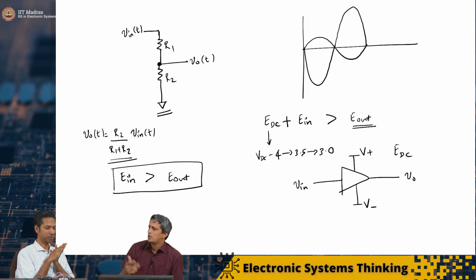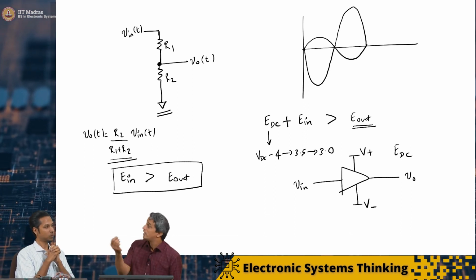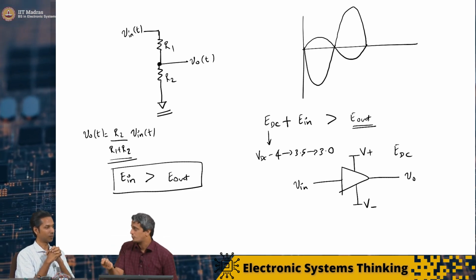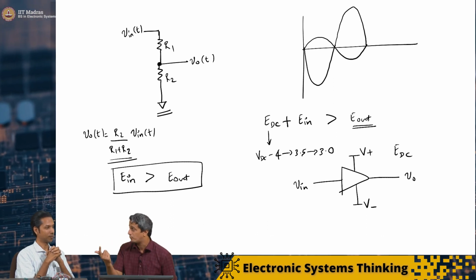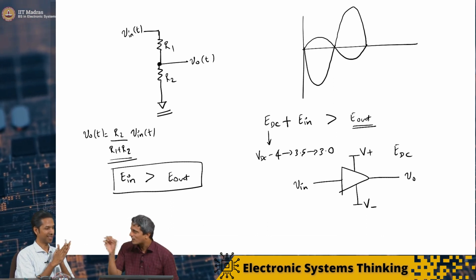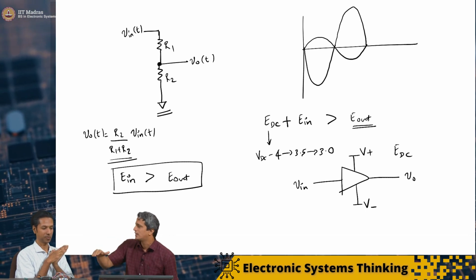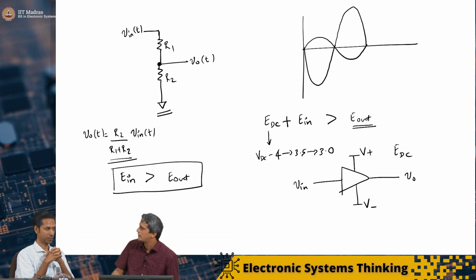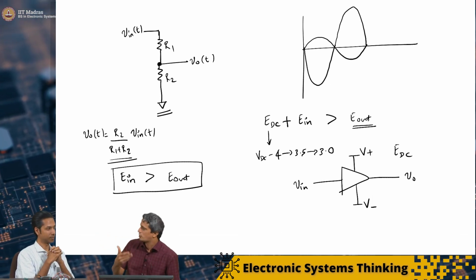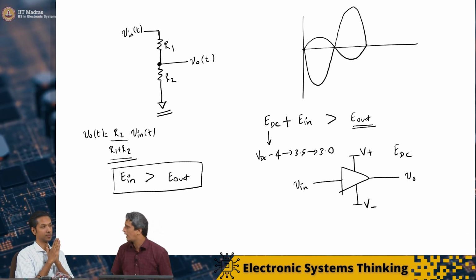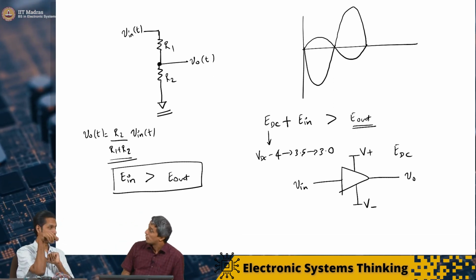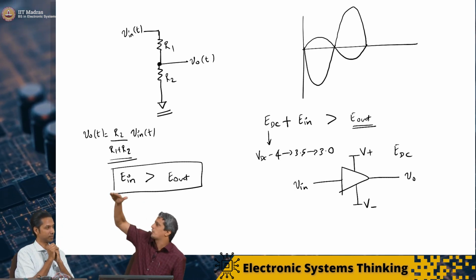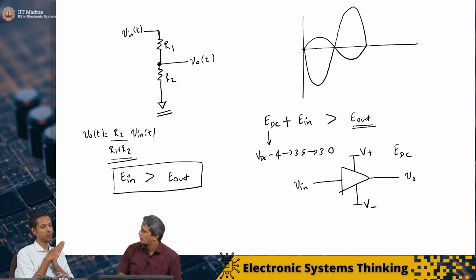In fact, in your laptop, in a VLC player specifically, there is this 200% amplification, which is not good for your speaker because you can actually hear it clip beyond the point. There's a sound. That basically means the speaker is clipping, which means the amplifier has produced an output that is saturated, and the signal is becoming more infidel. So saturated, you mean this clipping? Yes, exactly. Essentially the output has saturated and just remains at that particular value.